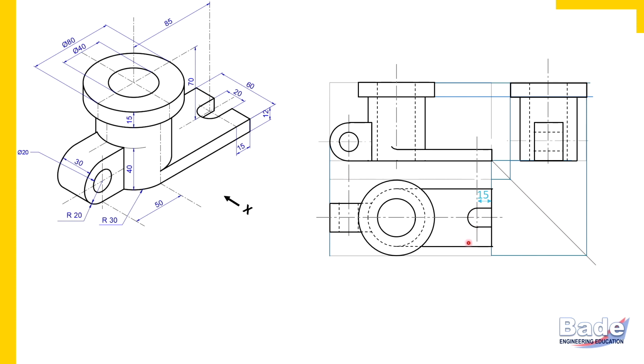But it is not a hole, it is a slot. A hole has a closed boundary, like the circular hole here. Also watch the hole in the U shape block. It has a closed boundary. But it is a slot, its opening doesn't have a closed boundary. Watch here, at the right end, between the top corners, there are no edges. So we'll have to trim that portion. Watch here. So this is how we have completed the U-shaped slot in the top view.